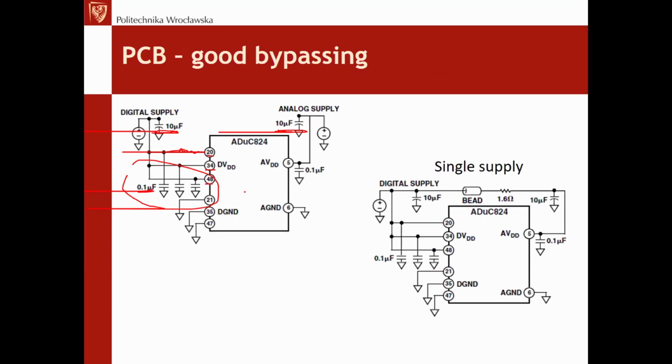But those decoupling capacitors are used as well for other integrated circuits, especially those that have digital switching inside, but also even for simple operational amplifiers. We shall use those decoupling capacitors to clean out the power supply signal.